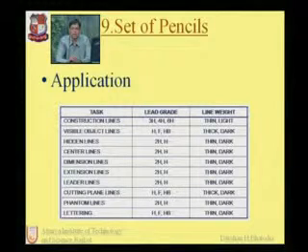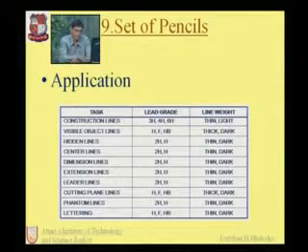Then the phantom lines, where the applicable lead grade is 2H and H, which is thin and dark. And the last one, if you want to draw alphabet lettering, meaning if you want to write any indication or alphabet in the drawing sheet, in that case lead grades H, F and HB are used, which have a line weight of thin and dark.